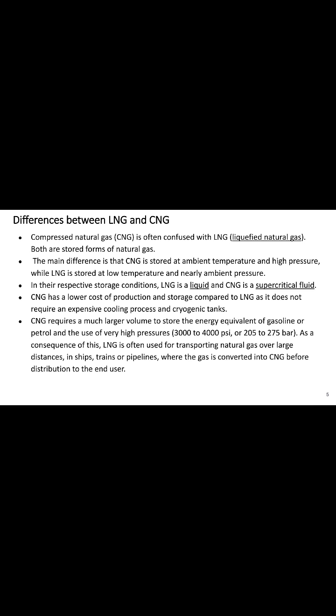Differences between LNG and CNG, liquefied natural gas and compressed natural gas. Compressed natural gas is often confused with LNG. Both are stored forms of natural gas. The main difference is that CNG is stored at ambient temperature and high pressure, while LNG is stored at low temperature and nearly ambient pressure. In the respective storage conditions, LNG is a liquid and CNG is a supercritical fluid.